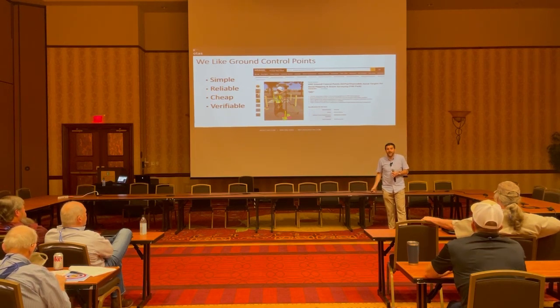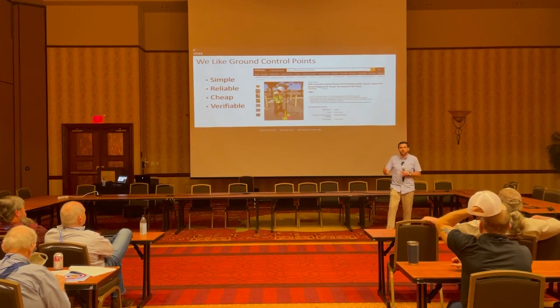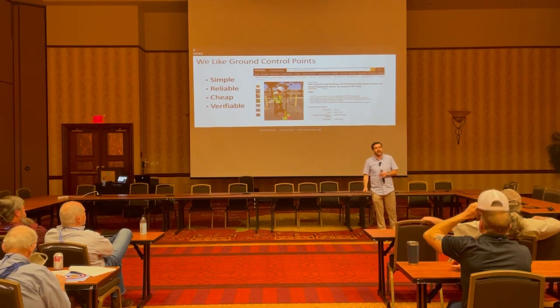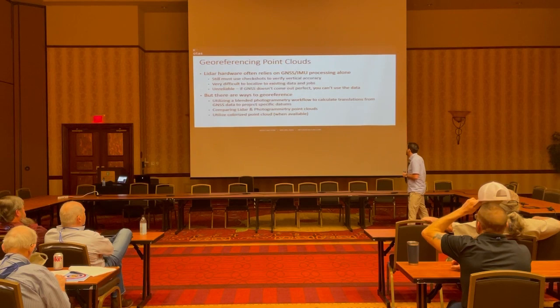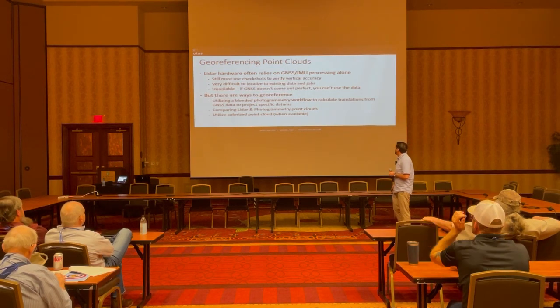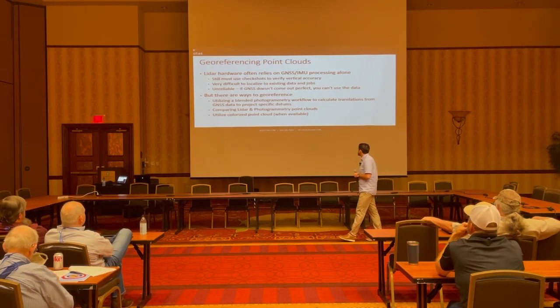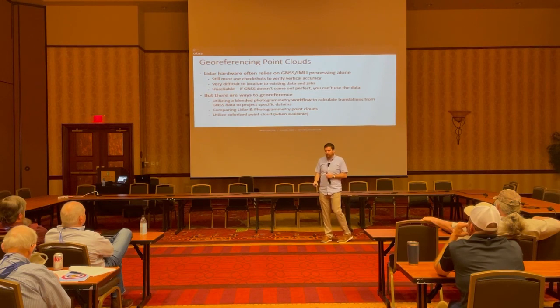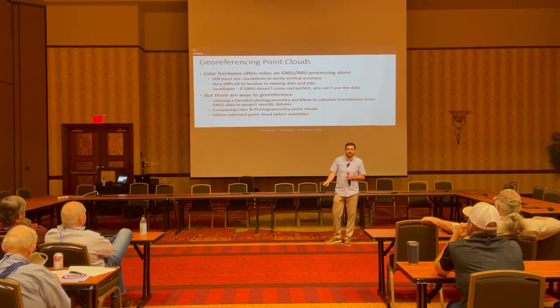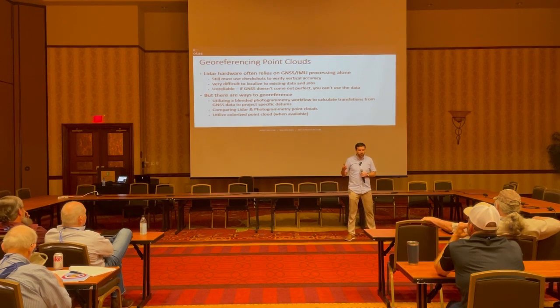I like verifying it, and that's why ground control points are so great. They let you verify your LiDAR data. I'm a big proponent of LiDAR. As far as georeferencing those point clouds, LiDAR hardware often relies exclusively on the GPS or GNSS system, and a lot of vendors really push that without any sort of ground control or ability to control.